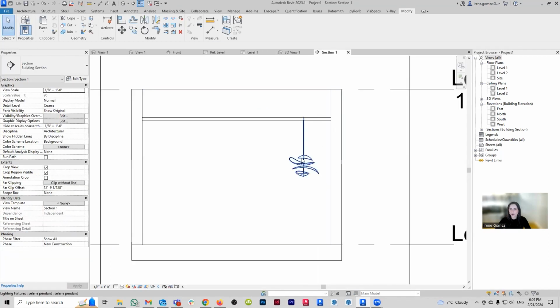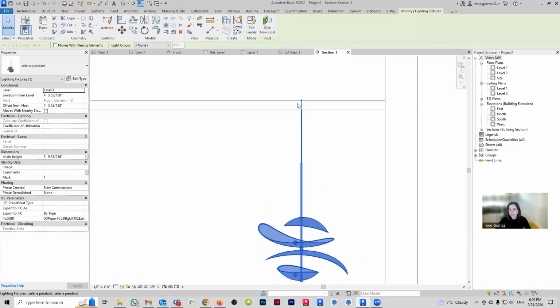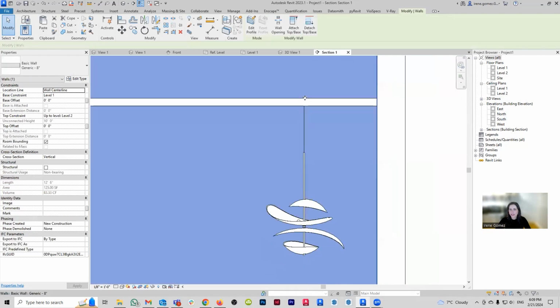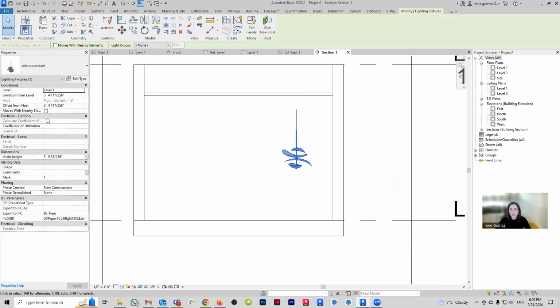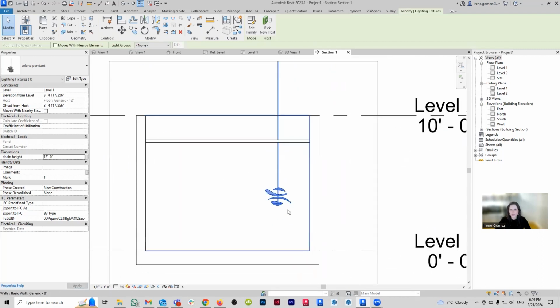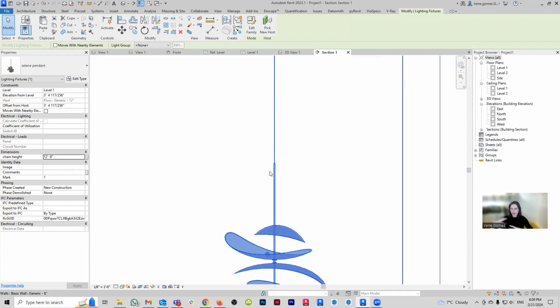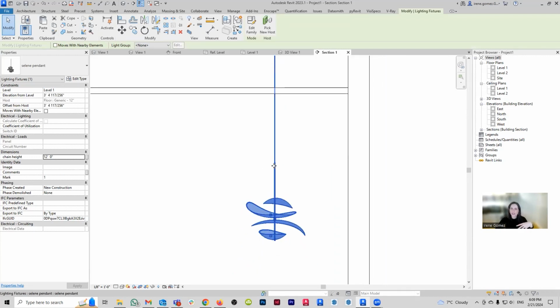And let's see what's going to happen now on the section view. I should get a little handle here that allows me to change that height. I'm not sure why it's not giving it to me. If that is the case, because I think if I change this, it will deform the whole thing. But let's see if I do 12. Oh no. Oh, there we go. Yeah, it seems to be working fine. So again, the reason that I was getting that error and that deformation is because when you're working with a revolve, you're not really going from bottom to top. You're kind of expanding in that 360, and that can sometimes cause issues with adjusting the height of things. So now I just need to play with this value or do some basic math.